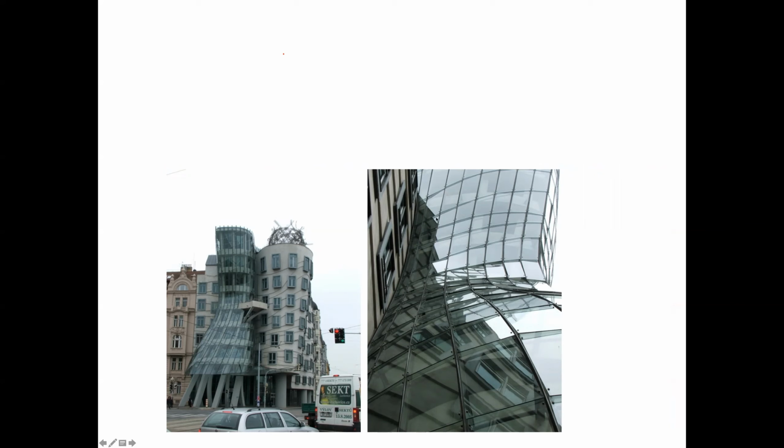But what's interesting here is you get these planar sheets of glass, and the whole idea is that they don't line up. There's no butt joint between the edges of the glass. In fact, what they do is they shingle the glass, and they purposely don't align it, in order to create this interesting texture effect. This is basically just a rain screen. As long as you shingle things in the correct way, you still get this thing shedding water, like direct rain and things like that, and snow.